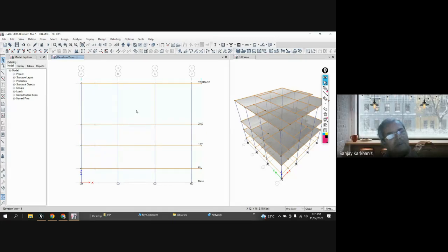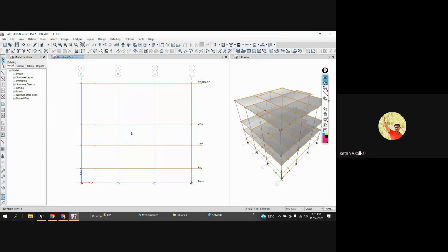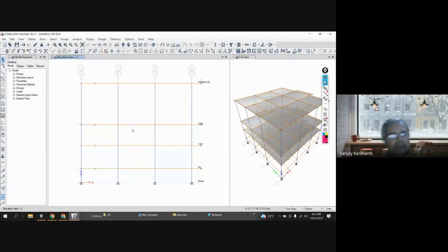No, remove the similar story option first, because what happens in similar story? See, the height of the column will be either this or this. It cannot be that the column height is different in a similar story. That must be why it happened. So that's why you are getting it correct right now.